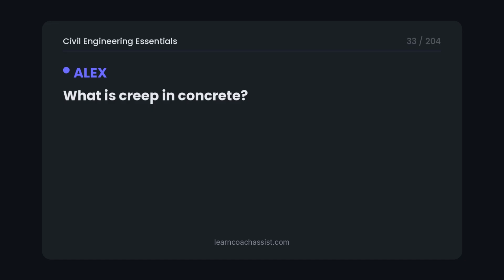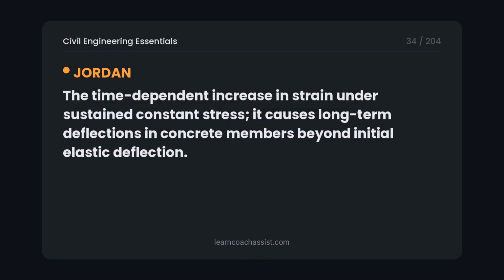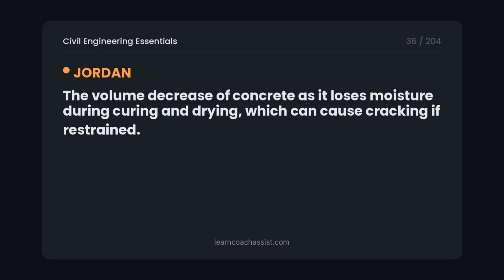What is creep in concrete? The time-dependent increase in strain under sustained constant stress. It causes long-term deflections in concrete members beyond initial elastic deflection. What is shrinkage in concrete? The volume decrease of concrete as it loses moisture during curing and drying, which can cause cracking if restrained.